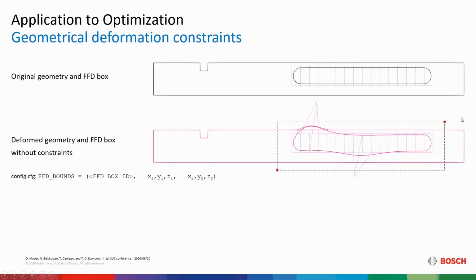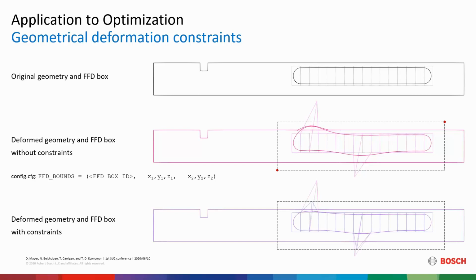During the shape optimization cycle, we will check if your deformed point will be outside or inside the box, and then project that deformed point that's outside of the box back onto the box. You can maybe see here that we keep the direction of the deformation, but we just limit the magnitude of the deformation. So we do not project this just downwards, but we take the gradient of the deformation. Maybe here it's even easier to see.